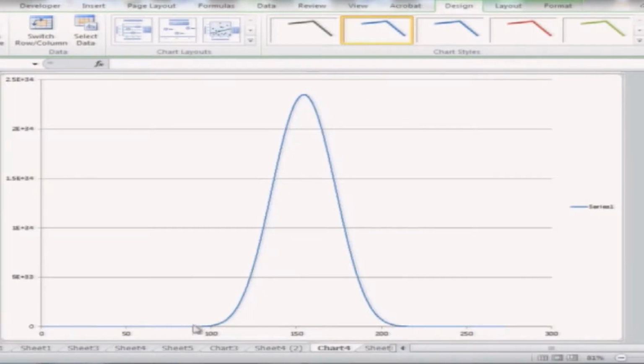Similarly, the critical undercooling would be around 42, but you can't see it in this graph because of the large scale involved. The critical undercooling is somewhere here, and this is the peak in the nucleation rate at about 153, 154 degrees, beyond which the nucleation rate starts to go down.